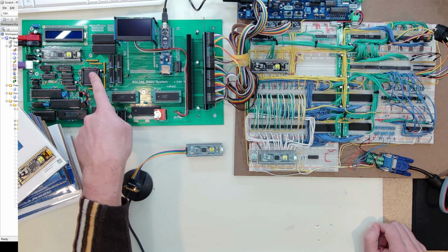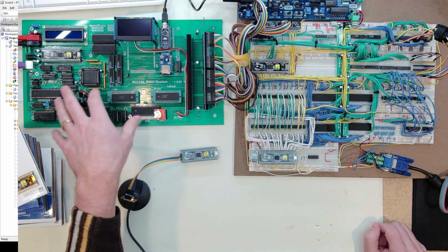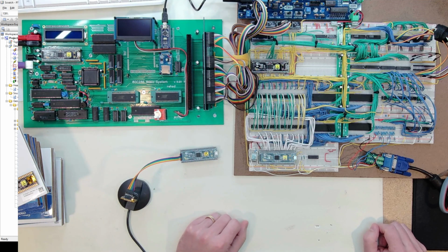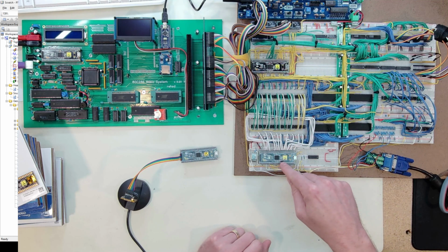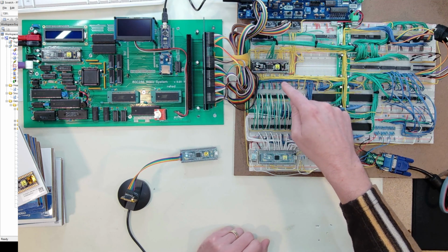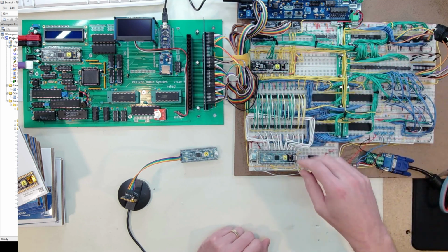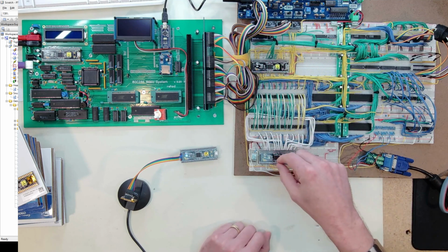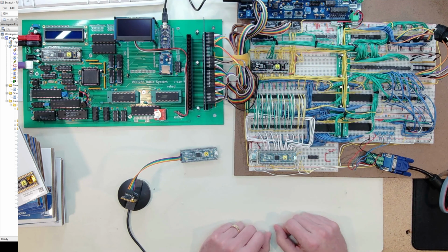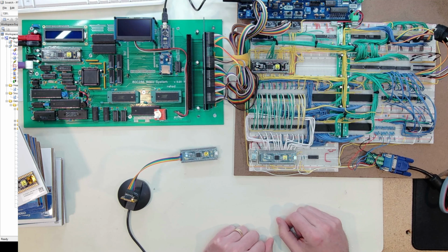I'm more worried about, can I work with the 286 and the bus controller and the math coprocessor and all the things that come with the 286 build. And for my video, I'm not worried about the simple things of generating the video sync signal or doing address decoding again up here. I'm worried about all the rest of this complexity. Can I learn that as I go? And so I'm taking the easier stuff, I'm simplifying it down to these PSoCs. Maybe at some point it would make sense to put PLDs in, but I would have the same argument. That's kind of the same level of cheating.